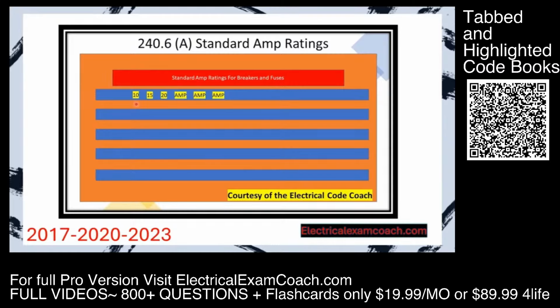If you're in the 2023 and later, it's going to start with 10 amps and go up. And in the 2020 and previous, it's going to start with 15 amps and go up. And then it goes up by fives: 15, 20, 25, 30, 35, 40, 45, 50. And when we get to 50, it starts jumping by tens and even larger numbers as we move up in amperage. The reason that this table is so important is it unifies the entire electrical industry.